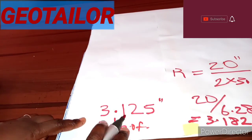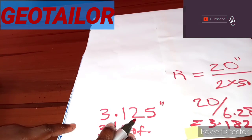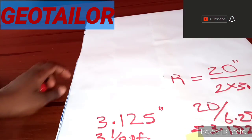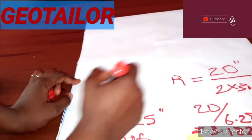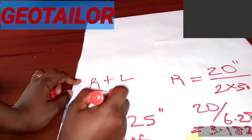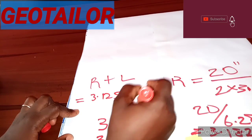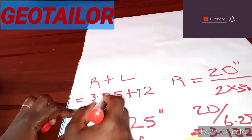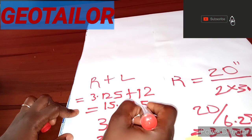Having gotten our radius, the next thing is to add our radius to our length of skirt. So our R plus L will now be 3.125 plus 12 inches, which is 15.125.